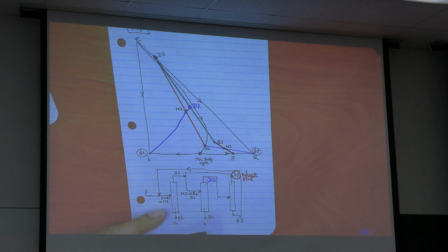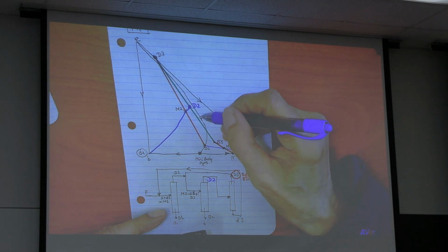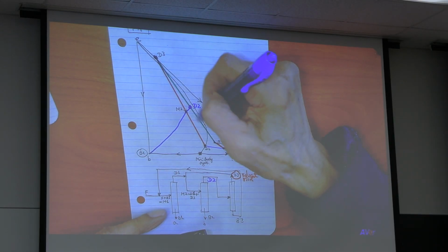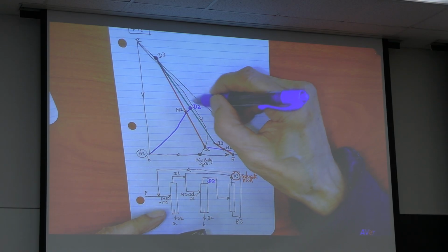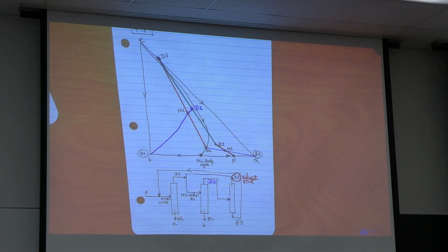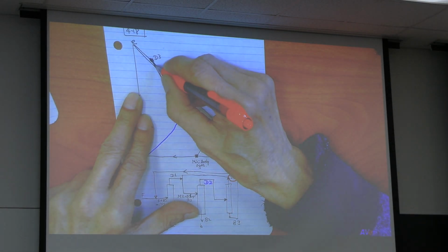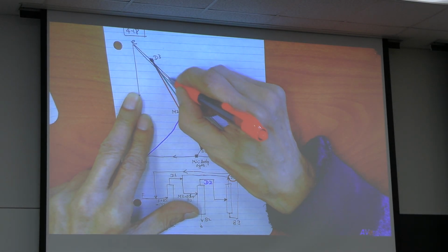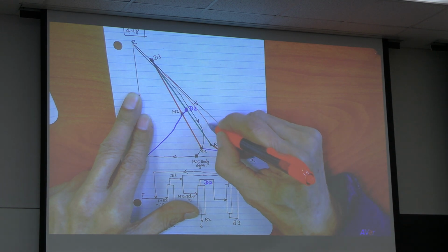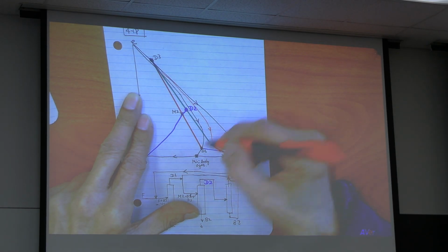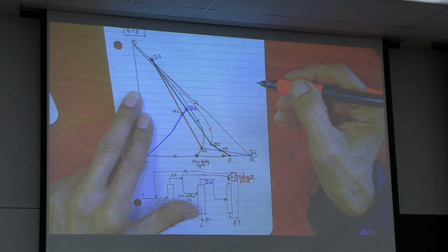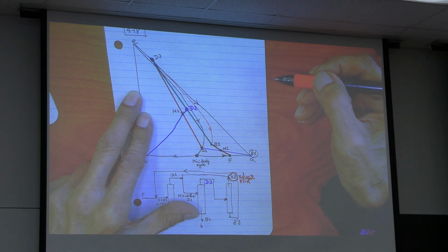I mentioned to you before, in the previous chapter, okay? So, this third column, even though the feed is here, on this side of the distillation boundary, your RC is on the same side of the distillation boundary, right? So this is no problem.